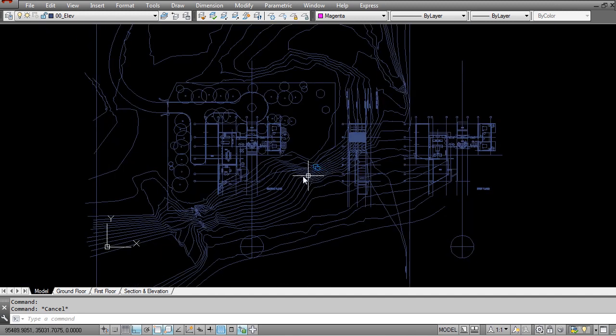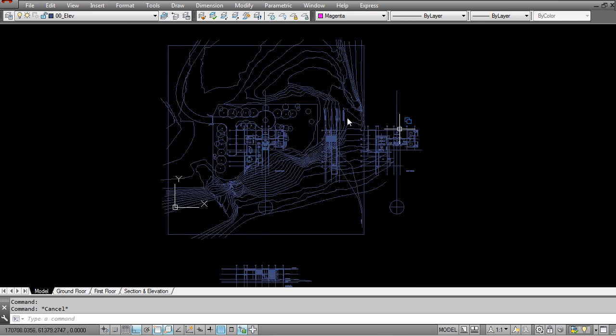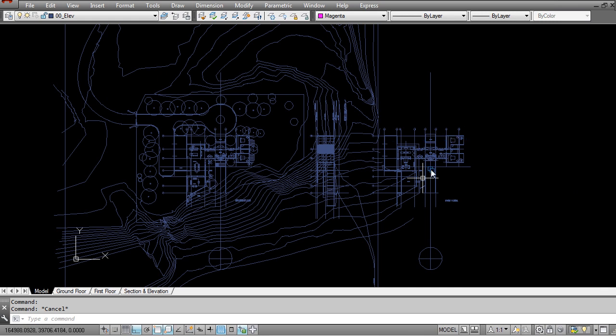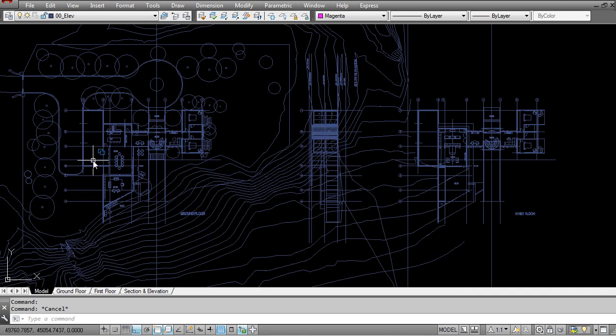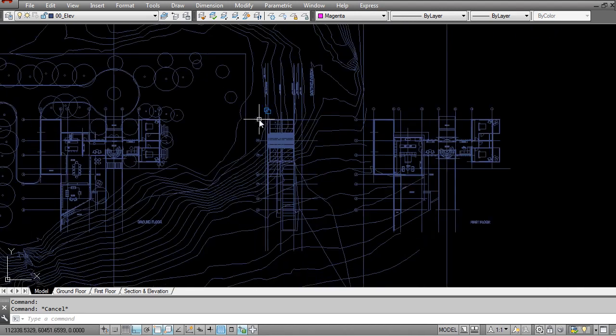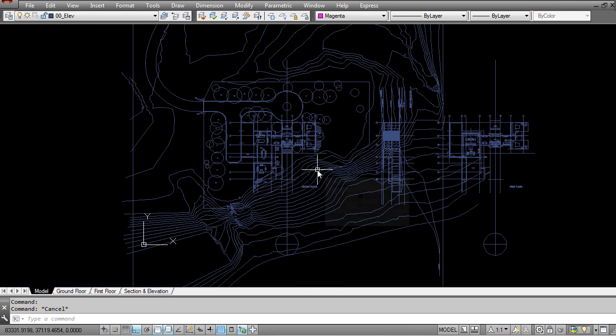Also, a good time to double check that all of your horizontal and vertical plans are aligned to each other. You want to make sure that your upper floor is perfectly aligned horizontally so that one isn't higher than the other, and that this also lines up with the side. By looking at your grid lines, you can draw a temporary construction line and see that everything is neatly in place. That's the best thing to do, and once all of that is done, you can be confident that your plan is at its most reduced and perfect state, and we will now import this into 3D Max in the next lesson.